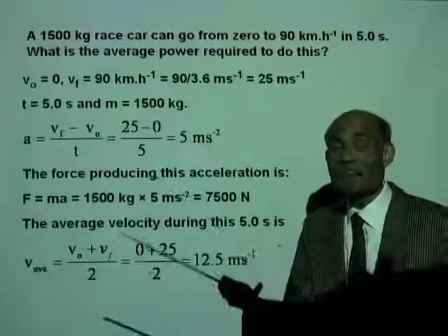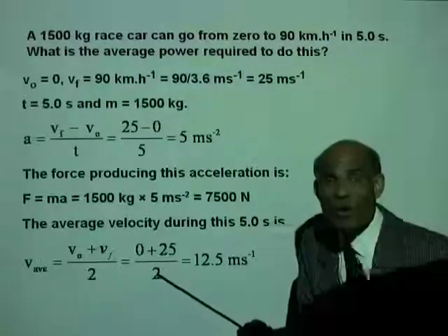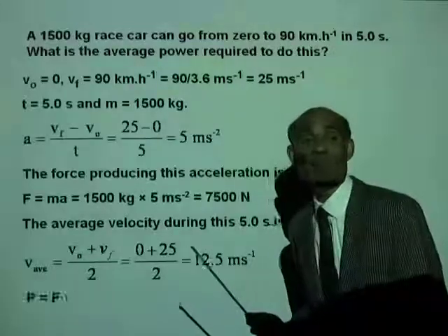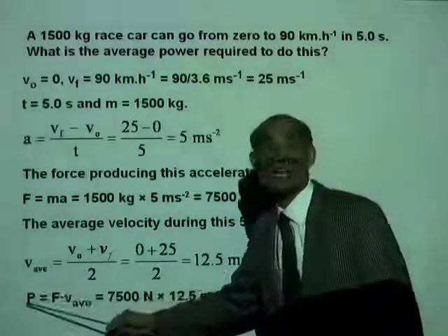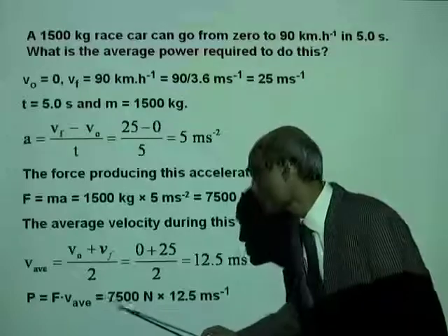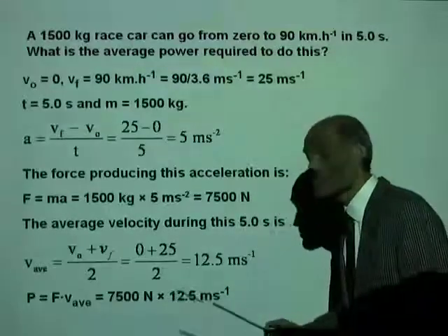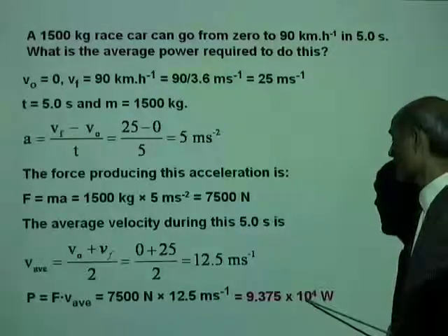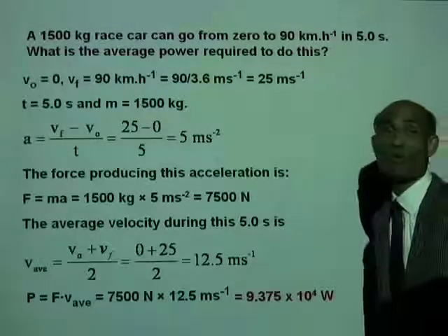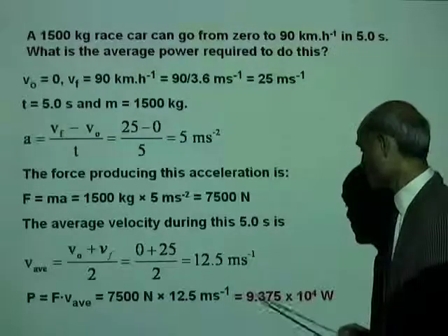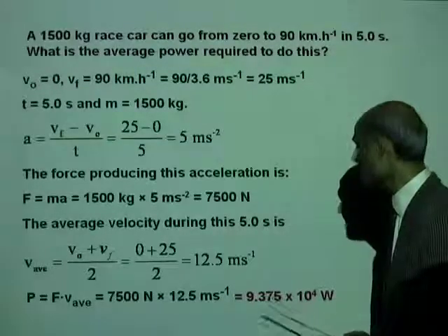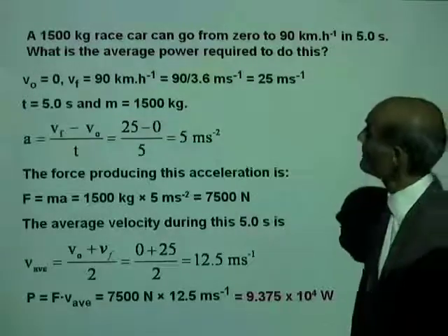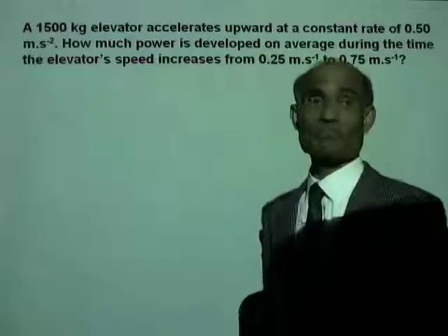Therefore, what is the average power required to do this? The average power is force multiplied by the average velocity. That will be 9.375 times 10 to the 4 watt, or which will be 93.75 kilowatt. All right, let's do another problem.